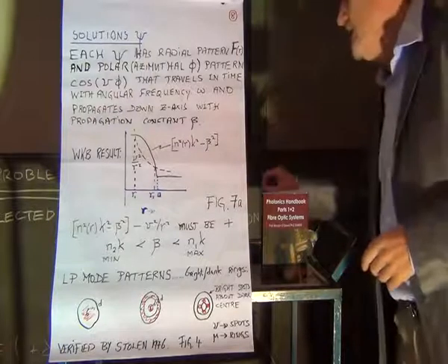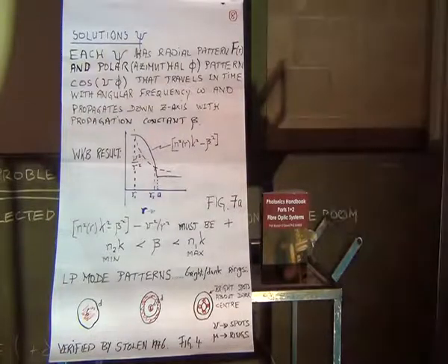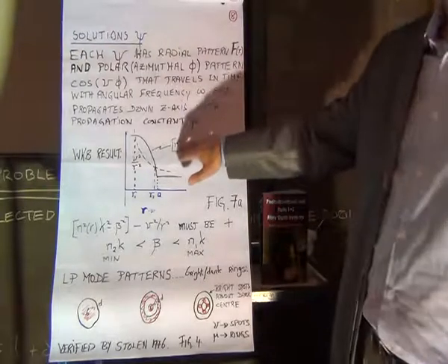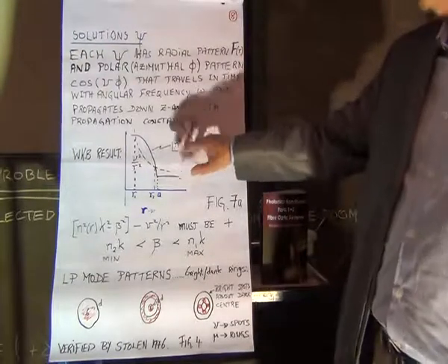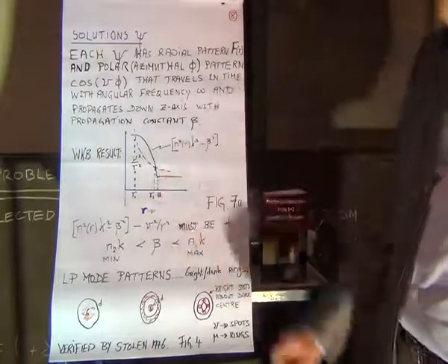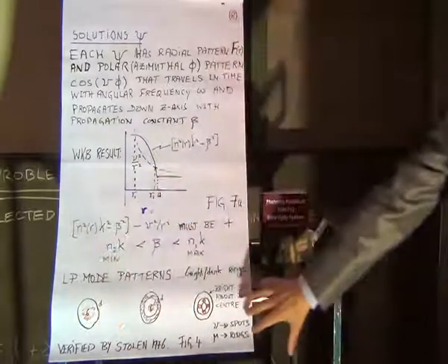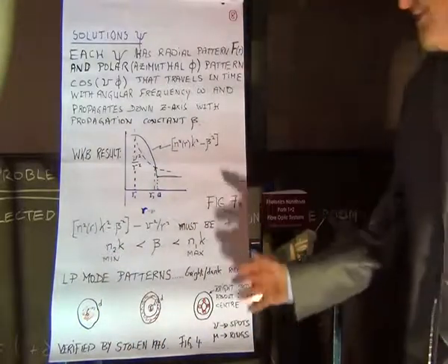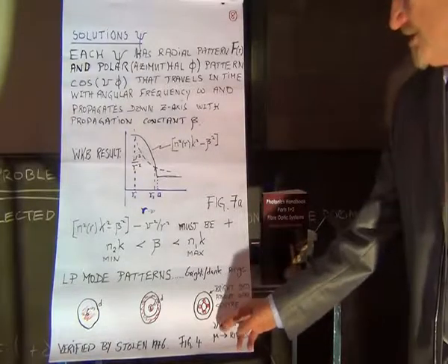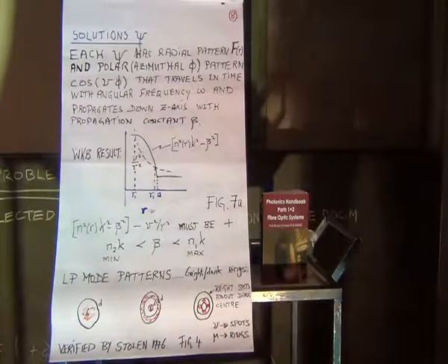This is exactly what the Gloge-Marcatili team did. They put n of r with different shape factors, gamma, into the wave equation. They solved it by the WKB method, and they worked out what the modes are, and what the beta value is. The beta value could be calculated once you knew the two integers, nu and mu.